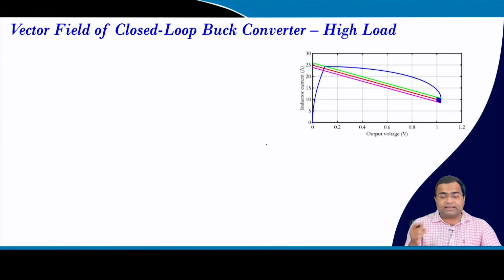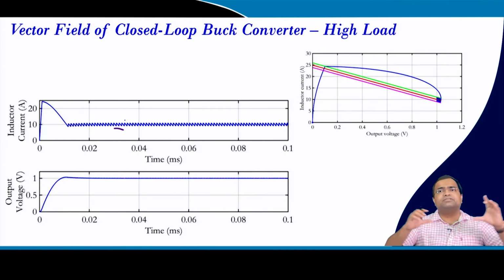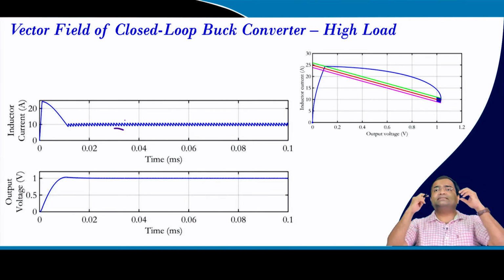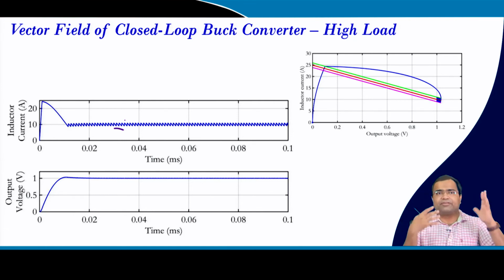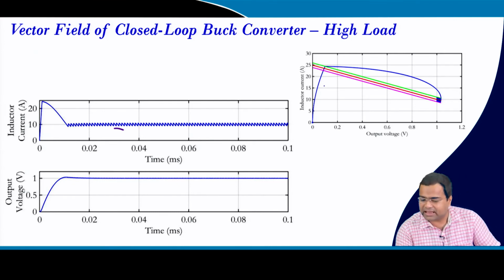And if we increase the gap, or basically the band, then you see this on-off operation and you can reduce the switching frequency. That means you can increase the ripple and the switching frequency can be reduced. So, by adjusting this band, we can effectively control the switching frequency, and that is one of the problems, but it can be addressed. This results in something like a variable frequency operation.